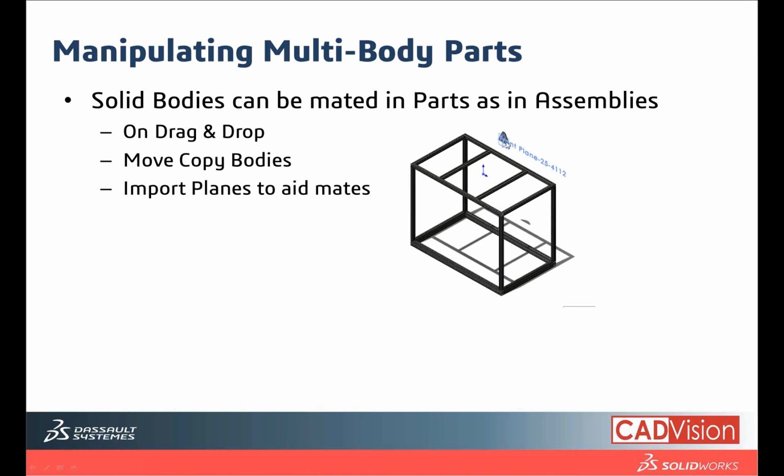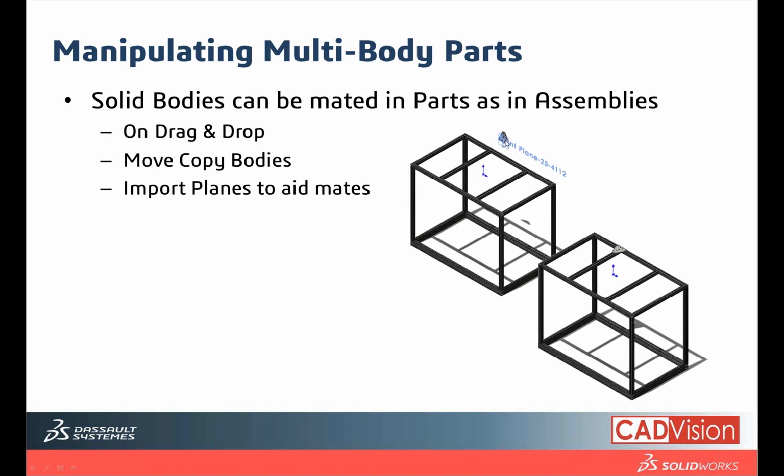And if you inserted a coordinate system, if I check on the coordinate system, if you have any coordinate system in the derived parts, it will show also. So the next thing will be repositioning it into this particular corner of it, so we can actually mate it together to the positions properly, just like in your assemblies, but with some additional steps.